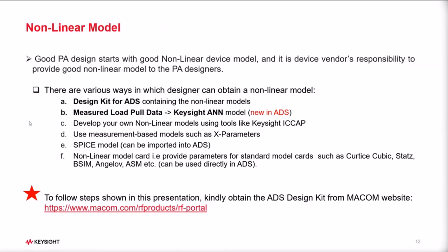Okay, so now let's begin our journey on power amplifier design. So where do we start? Any kind of nonlinear circuit design always starts from a nonlinear model. And it is essential, if you want to do a good design, you need to have a very good nonlinear device model.